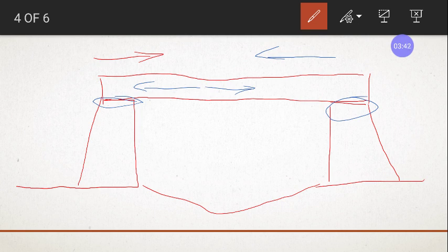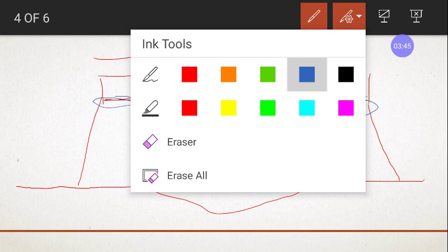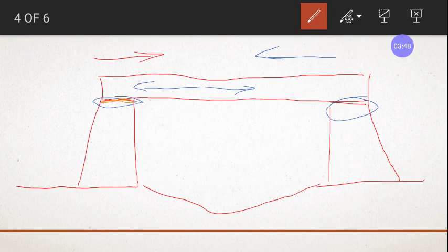So for that, we bring in a structure which will allow the movements, not to the full extent but to some extent. It will not fully move the superstructure; very small movements are allowed so that the stresses are counteracted. We allow it freely so the stresses will not develop. If I am trying to pull an object and it is free to move, there is no development of stresses, because as I pull or push it, it moves.